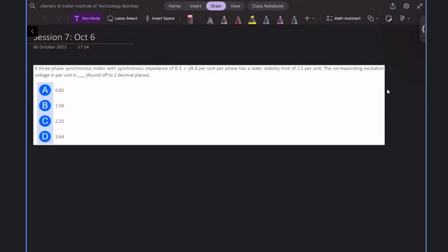Right? If your flux is over-modulated in your machine, if your machine is saturated, in that case, armature winding can produce a demagnetizing component of MMF. Otherwise, if your machine is under-excited, in such cases, your armature winding can magnetize the core of the machine.